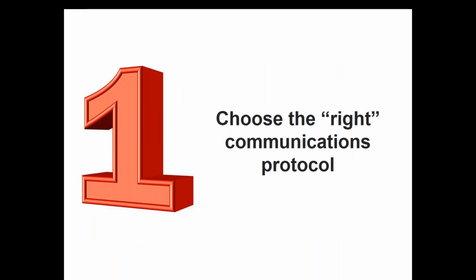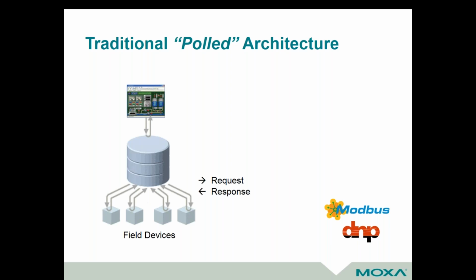But particularly in the new design stage, when you're doing an upgrade to an existing system or embarking on a new project, you really should spend some time on what is the means for communication that we're going to try to standardize on. So I characterize this as choose the right communications protocol. In our experience, most of you are probably using Modbus. It's really been the de facto communication standard on the plant floor, across the campus, and even wide area networking has been very popular.